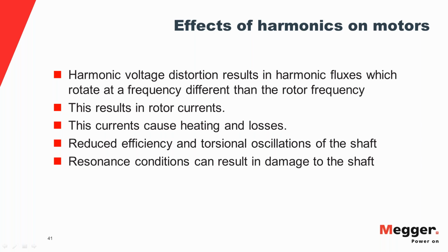Besides that, the interaction between the currents and the field results in a torque called pulsating torque. That's going to cause oscillations on the shaft. Now, if the frequency of the pulsations matches the natural frequency of the shaft, then that can result in a mechanical resonance that can amplify the effects of these oscillations, and can also result in damage to the shaft.